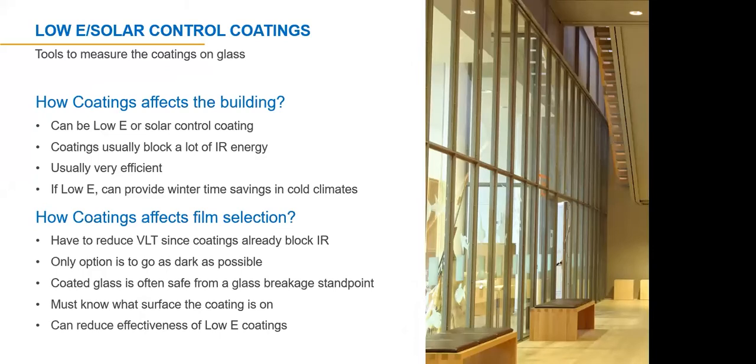Just like tinted glass, low E glass also increases the absorption. It's important to know if the glass in the window contains a low E coating. Most of these coatings are invisible and have very little reflection. For comparisons on absorption, a clear low E, low iron glass has the lowest absorption of about 4%. However, low E on a normal glass will increase to around 15%. If they use a triple silver coating, like Cardinal Low E 366, that absorption increases to 36%. If the window is also tinted with a low E coating, that absorption can easily go beyond 50%.